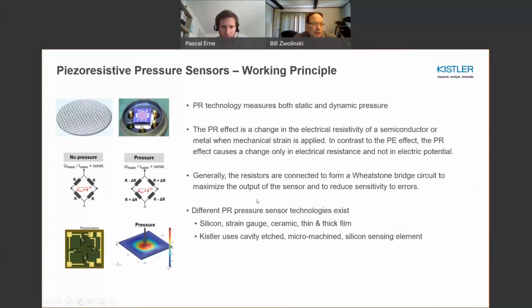So with piezo-resistive, as I mentioned, the change of resistance is proportional to pressure. And this is all very, very basic. A lot of times it might even be that the Wheatstone bridge or the resistance bridge is actually in an oil reservoir, which also provides very good media separation, and any thermal effects tend to be mitigated by virtue of the oil-filled capsules, for example.